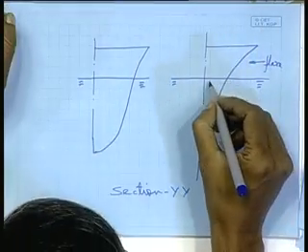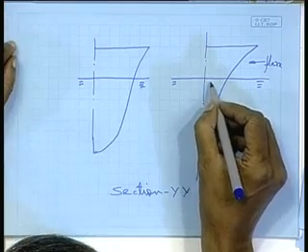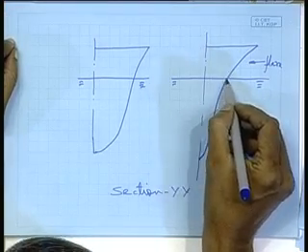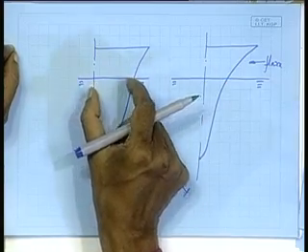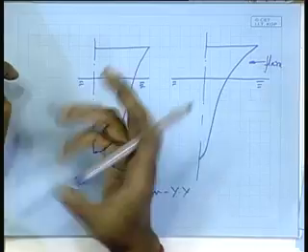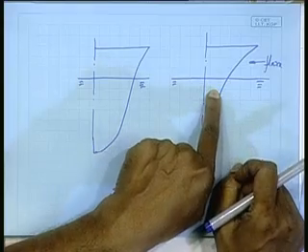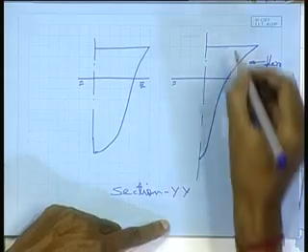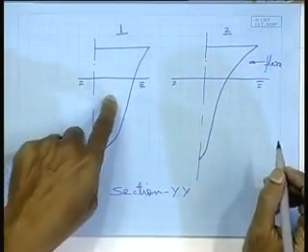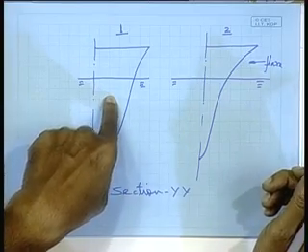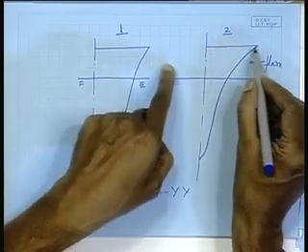So, in this what happens, you can see the water plane at the load water line is much narrower in this case compared to this. So, for a different hull form, for a different block coefficient, all these things you have heard about, some of those form coefficients, right. If the block coefficient is less, then it will tend to this type of a section, suppose this is number 2, this is number 1. With a higher block coefficient, it will tend to be like this. But in both the cases, I am having more or less the same deck area.